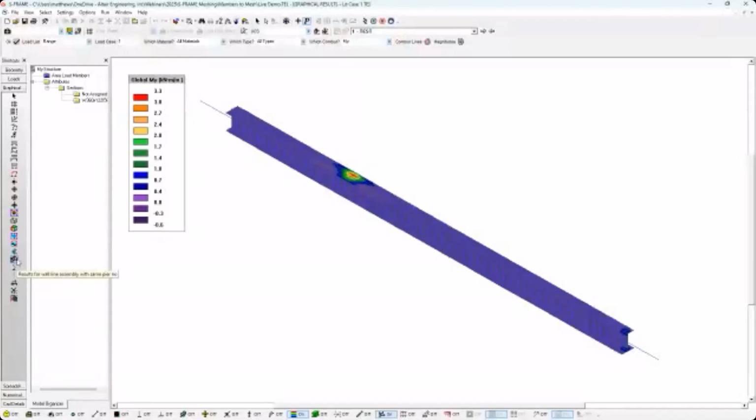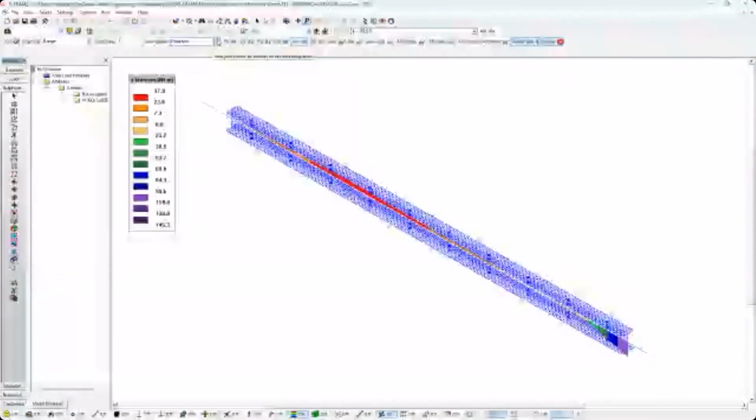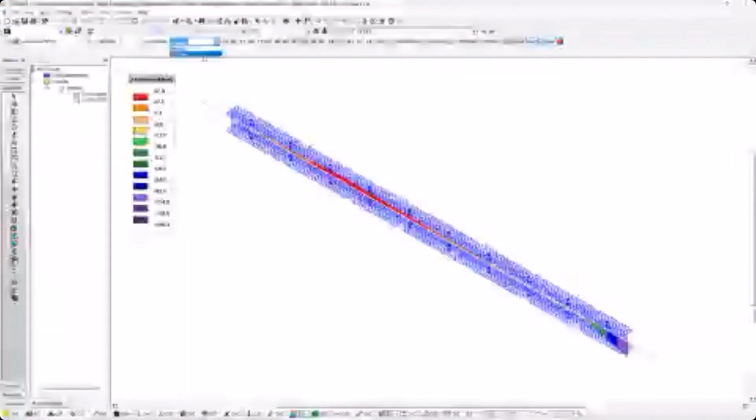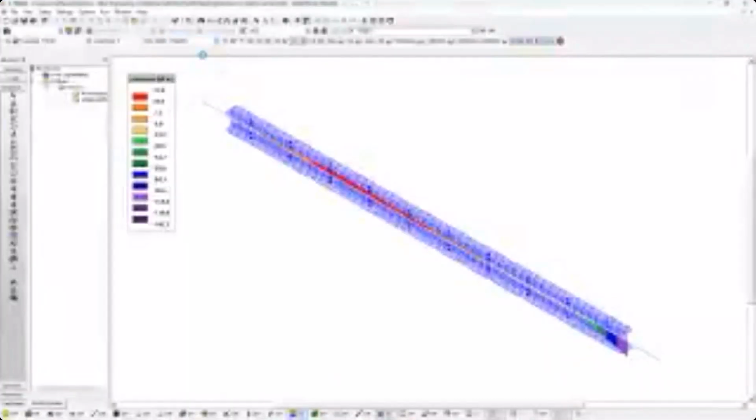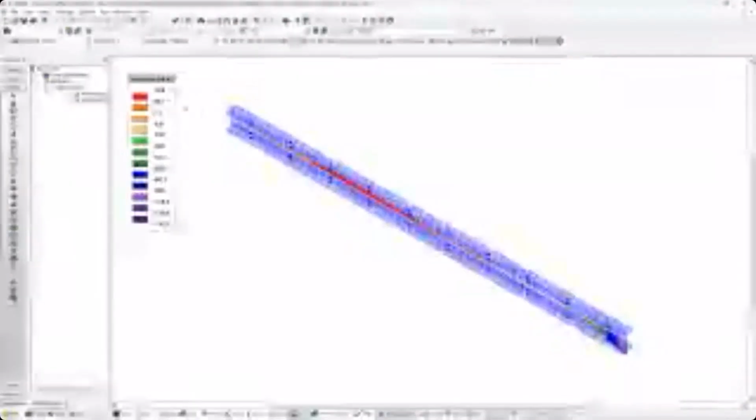We can left click and we can configure it to look at options. So there's the ability to look at, which is helpful for working with wall elements, for example. But if we're working with a member that's converted to a mesh, the diagrams option is a lot more helpful, I find. And it's going to allow us to look at things like the moments,